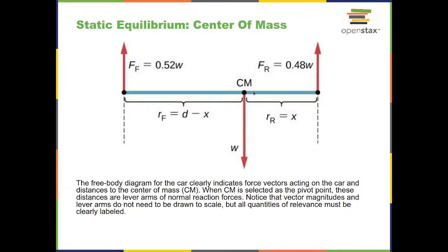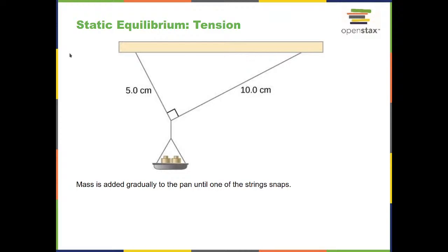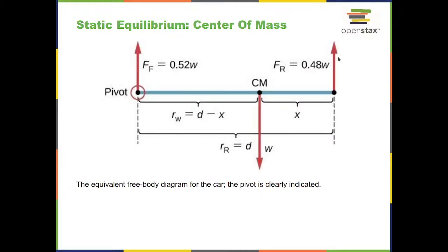So that means we can calculate the position of the center of mass from these forces at the front and the rear tire. Another example that the textbook goes through is the example where the extended nature of the object, of the mass distribution, can be ignored. So in this case, there's just a single point mass that has all of the weight that is added to this span here. And in that case, of course, the torque equation disappears. So in some sense here, we didn't have to use the force balance equation.